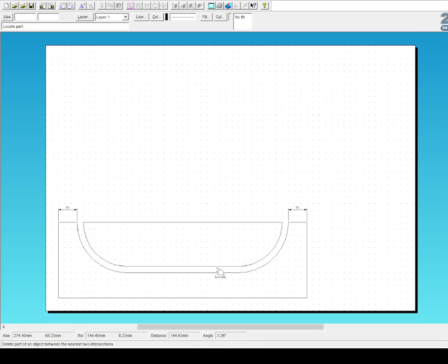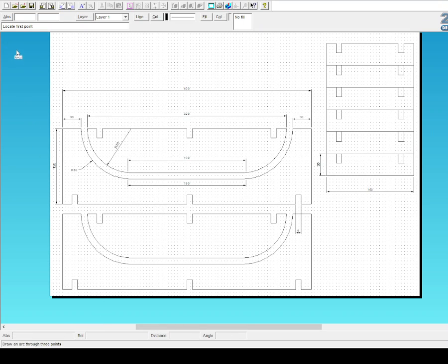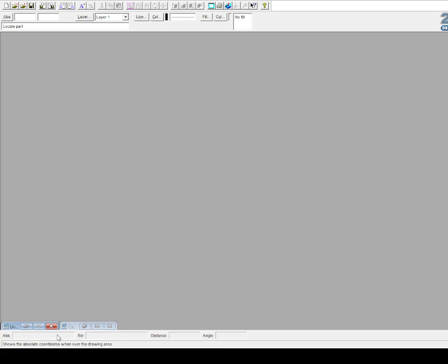What I want to include now is a couple of squares which are 9 millimeters, and let's check our depth of each of those squares and make sure we're doing the right thing, because if you get the depth of these wrong then it can be problematic. I'm just going to switch off my grid lock, go back to attach because it's an odd number, and that's actually 15. So each of those boxes is 15 by 9.